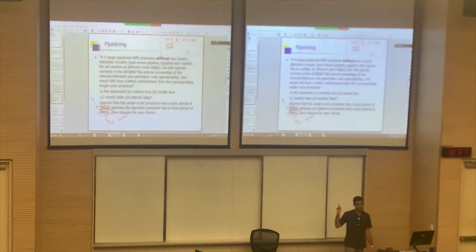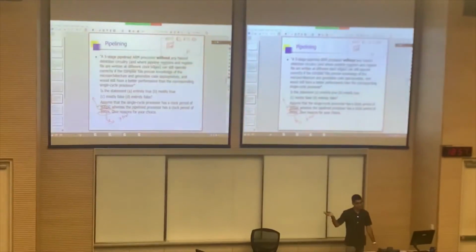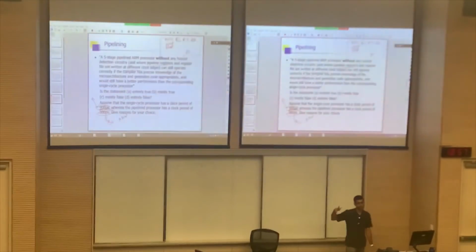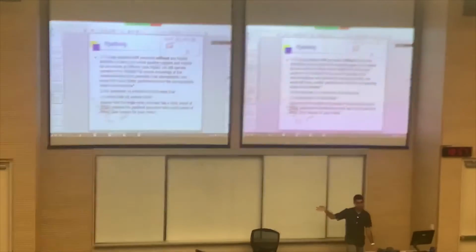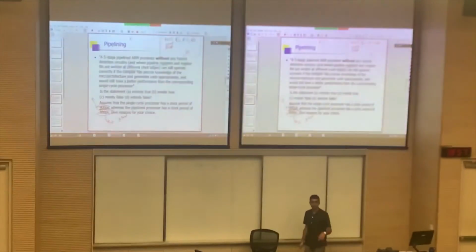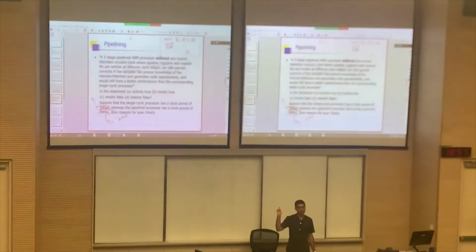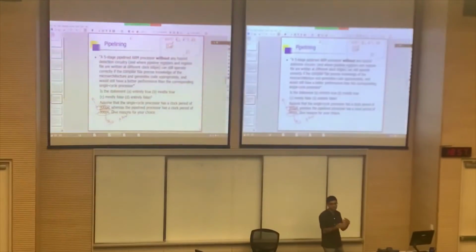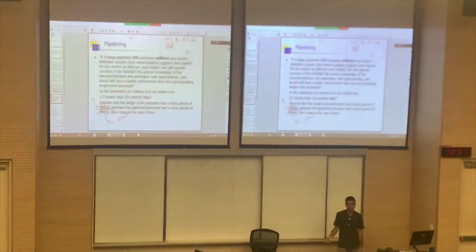But now we haven't considered control hazards. For control hazards, depending on the stage, you will have to have a certain number of NOPs after that. For example, if you are taking your branch in execute stage, you need to have 2 NOPs per branch. And here again, you are looking at 1 out of 3 being useful. So only in an absolute worst case scenario, your performance will actually tally. But in practical scenarios, you will have more than 1 out of 3 instructions that are useful.